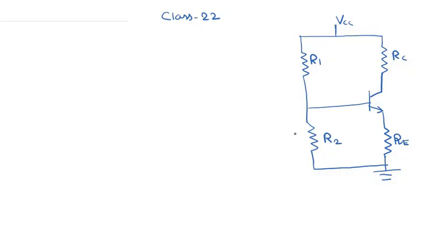So this is our voltage divider biasing, and as I stated earlier, the AC voltage is actually put through this capacitor Ci over here like this, but this AC voltage is not a part of the biasing network. Right now we are interested in how the circuit is biased, or what are the biasing current and biasing voltage, or what is the operating point basically.